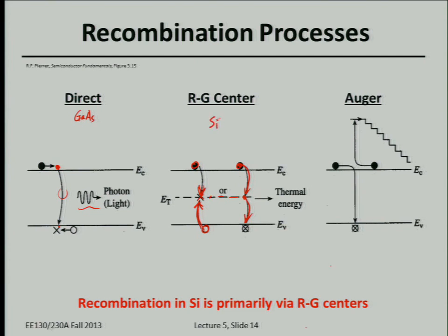How does adding energy to an electron in the direct case cause it to go to a lower energy? Well, in the recombination case, electrons need to emit some energy. But for the generation case, if you go back, if you remember, by inserting those trap centers, we can provide a smaller energy for the electron to absorb, right? And then later they're going to trigger the second step.